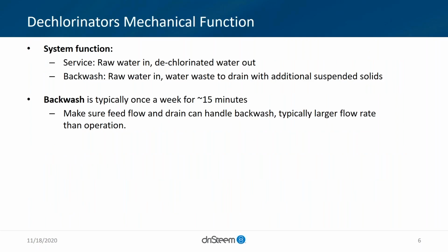Again, a brief description of the function. This is a lot simpler than a softener. Regarding our offering, during service, raw water comes in, goes through the control head, which I'll show in a moment, down through the activated carbon bed, and is collected and brought back up through a clean water tube. I forget as we're doing these webinars, you guys can't see me, but "clean water," in quotes. Obviously, it's only really functioning on the chlorine aspect of things and doesn't remove other, let's say, inorganic dissolved solids.